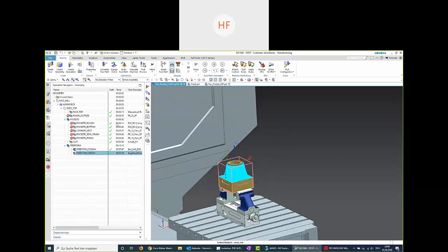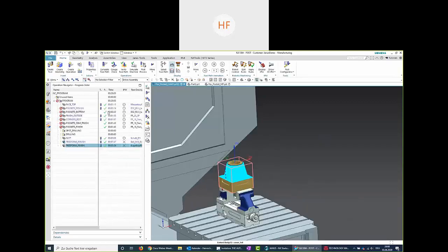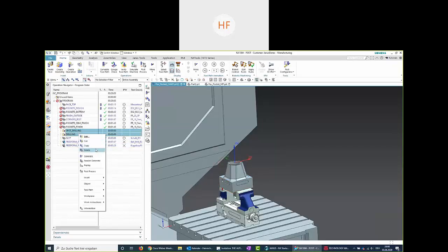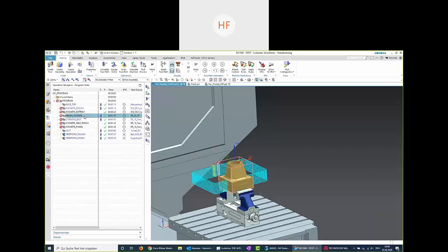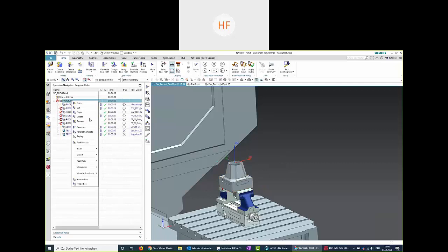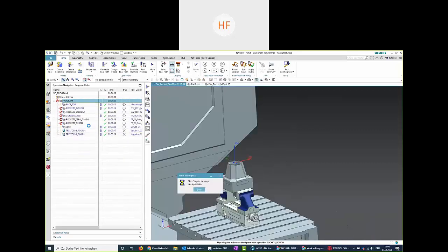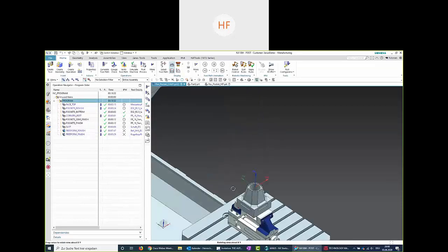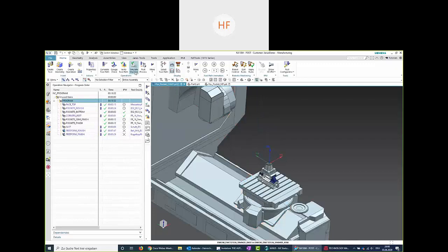All those settings are correct. Good. What else is not necessary? For instance, the finish outside operation. It's been this one here, no longer necessary. Right click and delete. I will make a regenerate around all the part. Maybe that turn. And the part, once more, is finished.